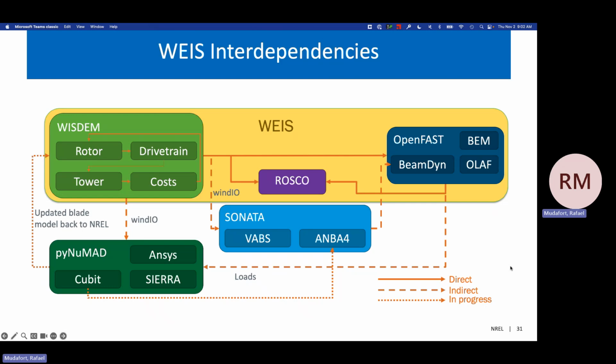Anytime you do anything that requires a new code, there's an evaluation. The fast tool has three levels of difficulty. OpenFAST is like the highest level. Time-based condition, CRAFT is the lowest level, frequency domain. And the middle level is called linearized FAST. So you can linearize everything, and change between the three levels. You can generate all of those graphs.